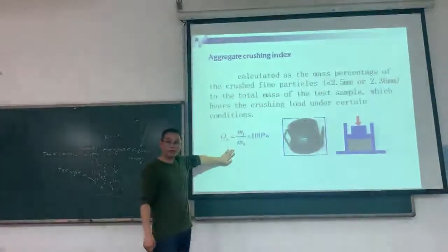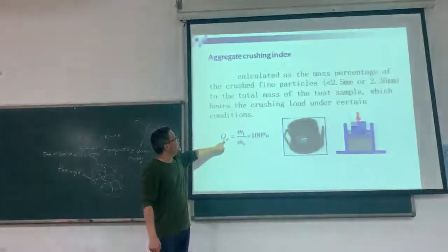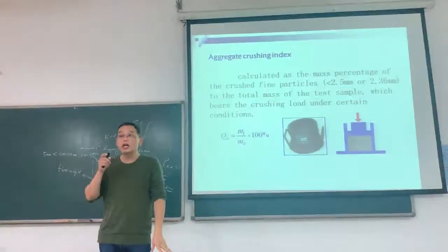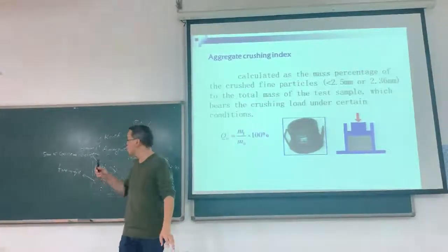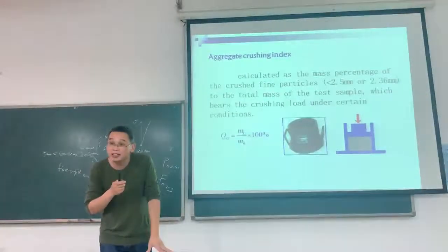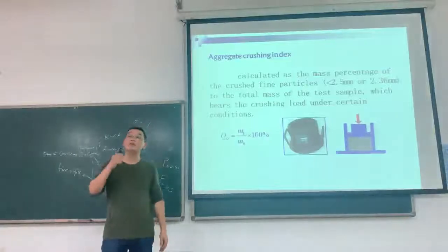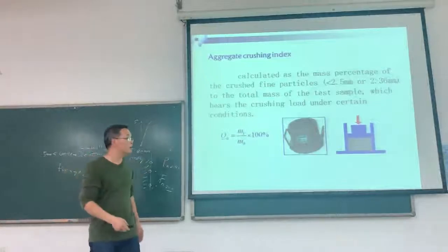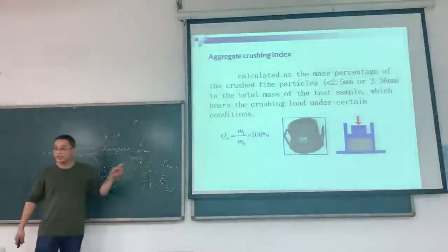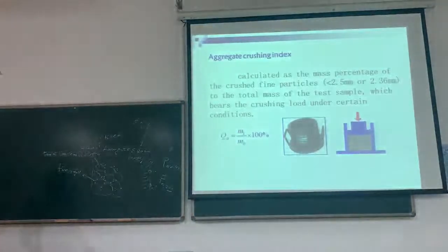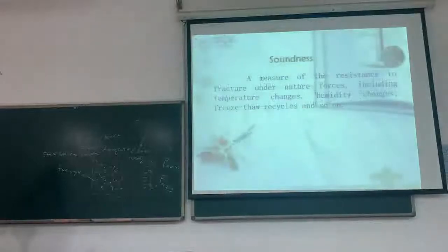So, I'll give you a question. If the aggregate crushing index is bigger, it means the strength of the aggregate is good or bad? It's bad. Yes, because the crush is so big. So this is a very important index for the application of the aggregate. Okay, it's good.